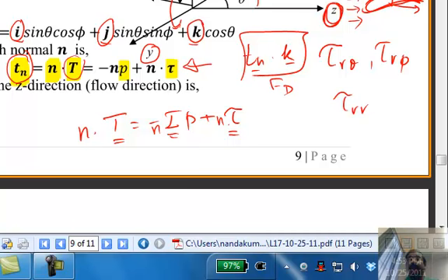Physically the argument is it is 0 because it is symmetric. So for every force that acts this way, you can decompose this force in this direction and in that direction. Similarly you can decompose this force in this and in this direction. So these two forces would be additive. They will add, but these two forces will cancel each other out. So there will be no net force. But for an aerodynamic shaped object, that won't cancel out in the vertical direction. That's what gives rise to the lift force. That's called a lift force.